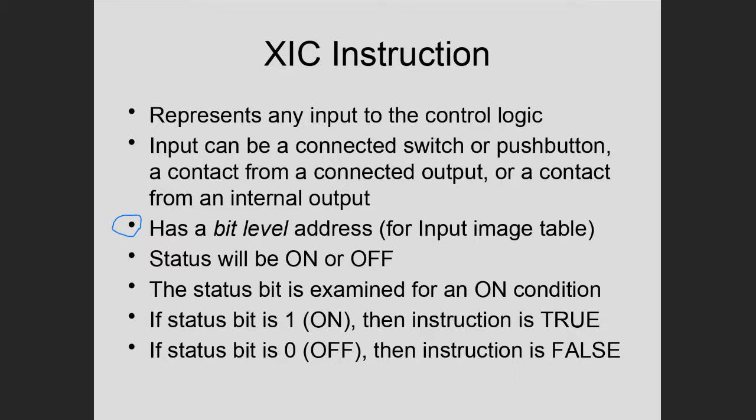Now you've got to remember what we said about digital devices. Typically, in a digital device, the smallest piece of information you can access is a byte. When you use your cell phone or computer and type the letter A or B, that letter is stored. The code is called ASCII code, and it's represented using 8 bits or 1 byte. When you move information around, you move around bytes or kilobytes or megabytes. You can't move around bits. PLCs are different. You can actually address a single bit, and that's what these commands do. This particular command examines a single bit in a register, and it is not word-oriented, it's bit-oriented.